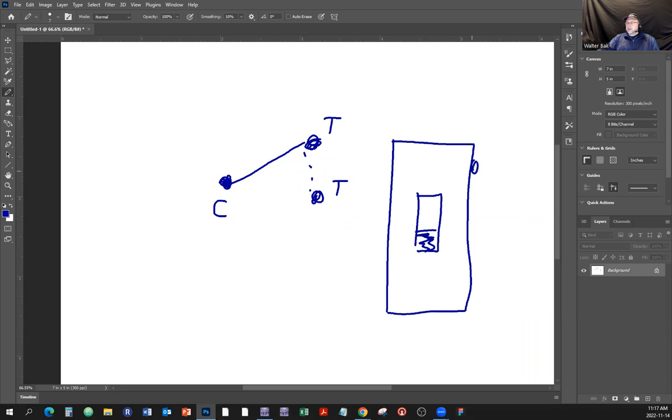And here is one screw terminal, here is another screw terminal, and here is another screw terminal, and it's called a three-way switch, which is the single pole double throw. But in the electrical industry, they call it a three-way switch because we can get three ways into that. Way number one, way number two, and way number three. There are three connections that we have.